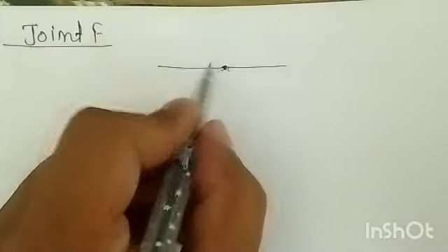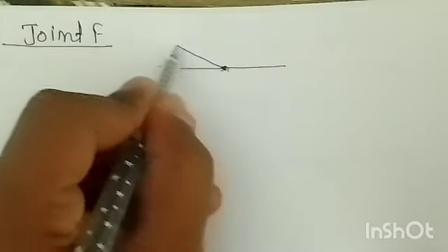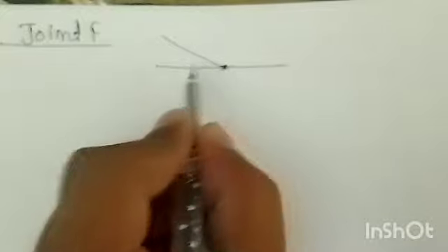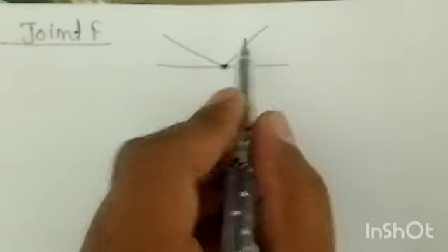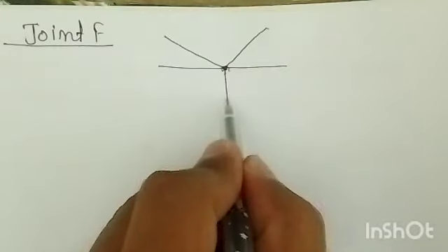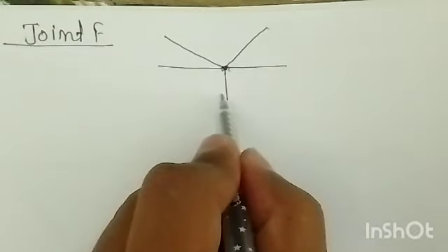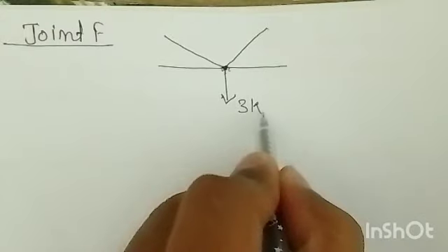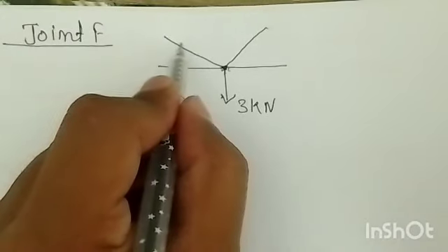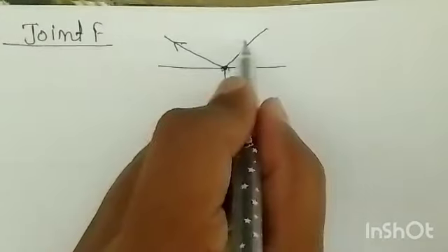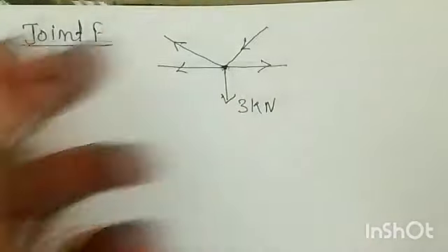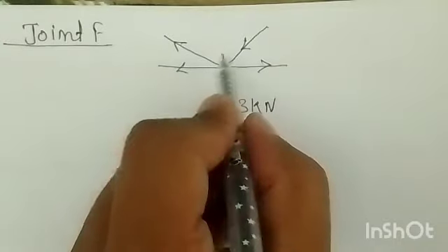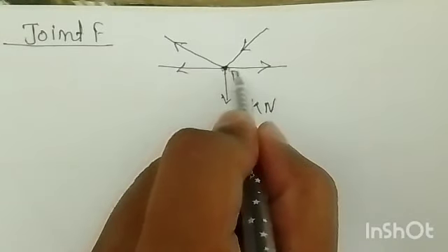You can refer to your question, because every time I can't turn the pages. So this is your CF, this is your DF, right? And this is the vertical load which is acting downward, 3 kilonewton, right? So this is tensile. Why? Because the previous one was tensile, this is compressive, this is tensile, and it is tensile away from the point. So this point is named F, right?